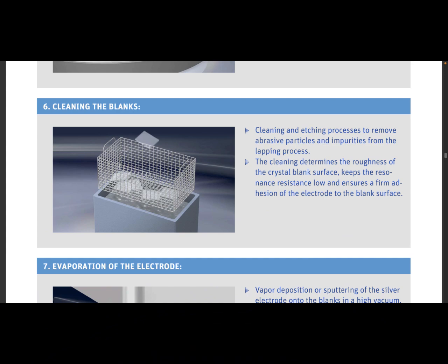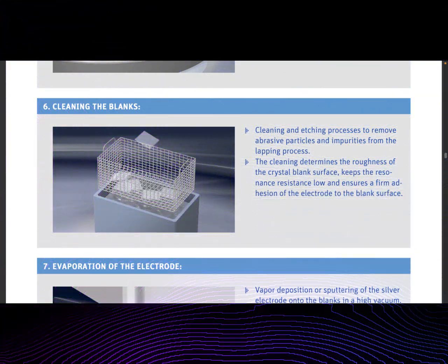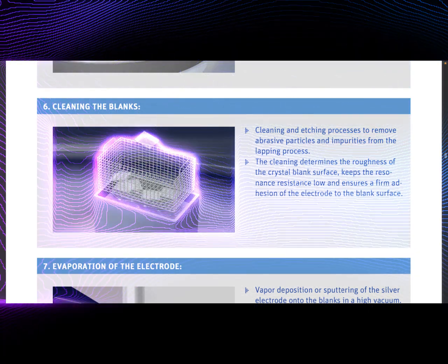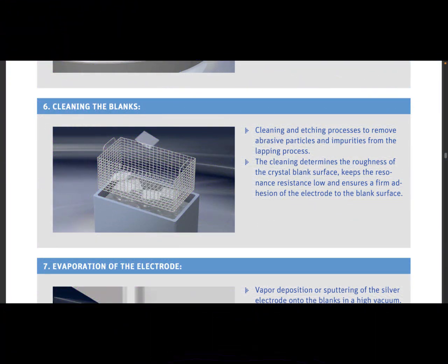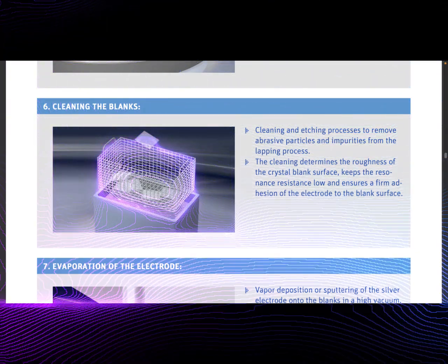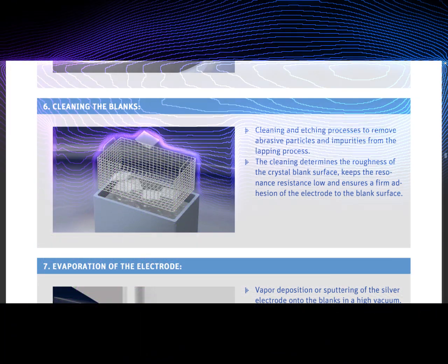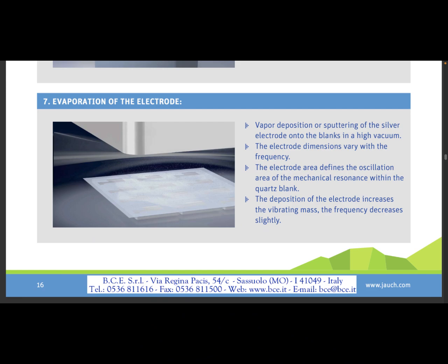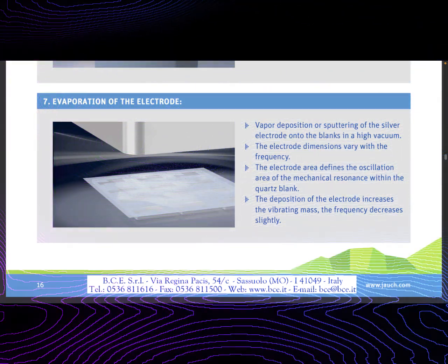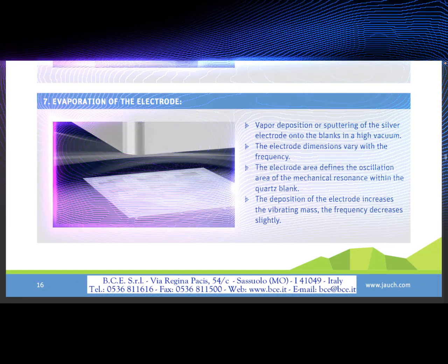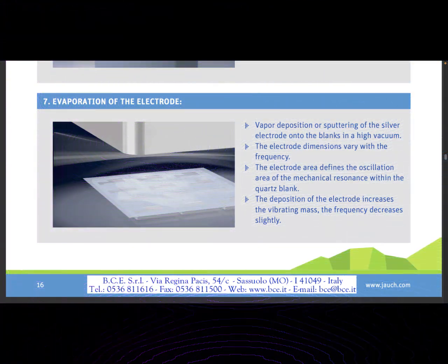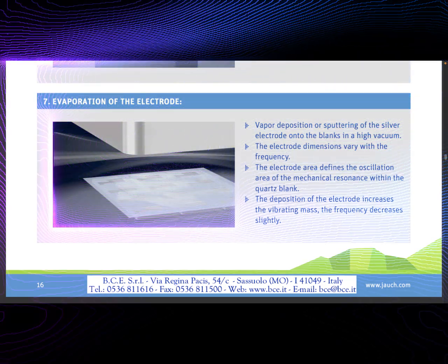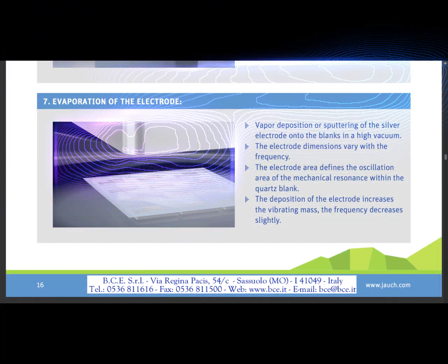ESR, equivalent series resistance. The equivalent impedance of the crystal at its operating frequency. ESR values are generally stated as maximum values and are expressed in ohms. A higher ESR requires the oscillator circuit to have a larger negative resistance, at least 5 times ESR, to ensure startup.